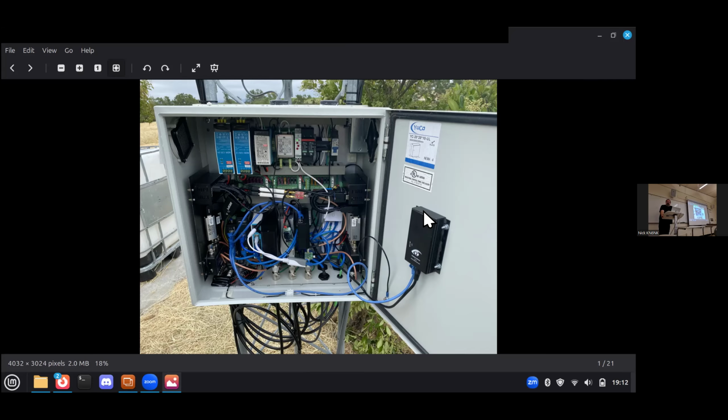How is temperature and moisture control in this box? I've got vents on the sides up at the top and an intake fan down at the bottom that is controlled by a thermostat. Once it hits about, I think, 85 or 90 Fahrenheit, the fan kicks on. And then when it drops 3 or 4 degrees below that set point, it turns off again.